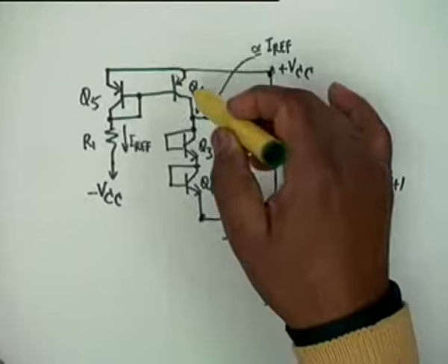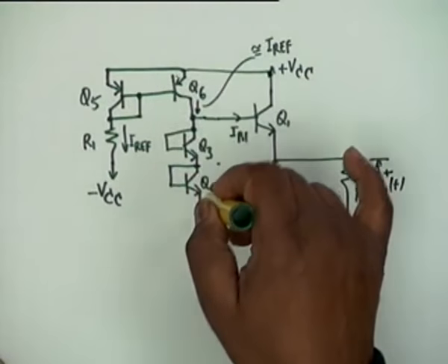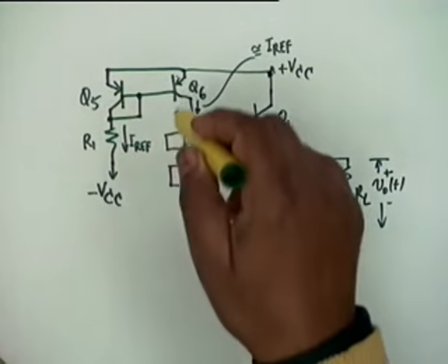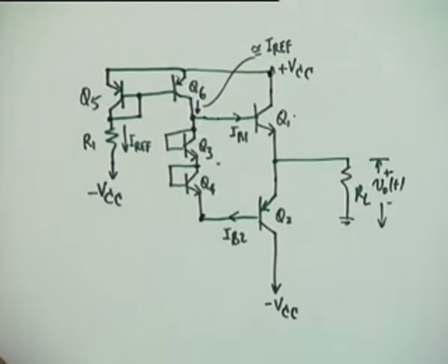Because the larger the current drawn from the transistor, the more will be the dissipation, and the more will be the junction area required to supply this current. Otherwise the transistor will burn off. Okay? So the emitter junction area for Q6, Q5, Q3, Q4 can be much less as compared to that of Q1 and Q2. Now what does this affect?